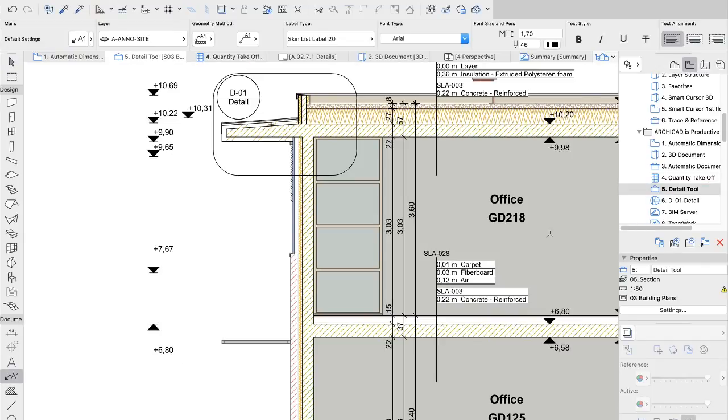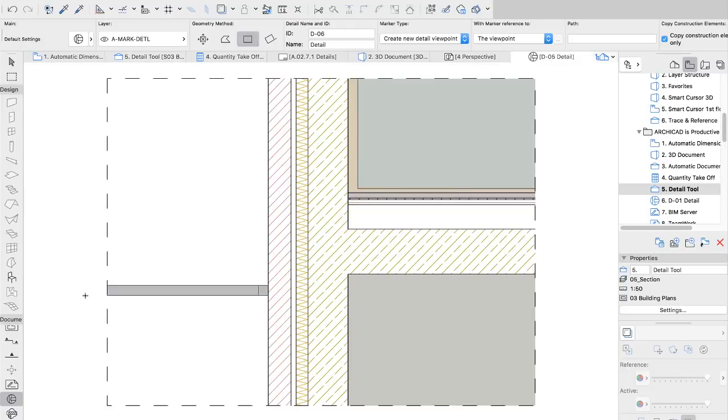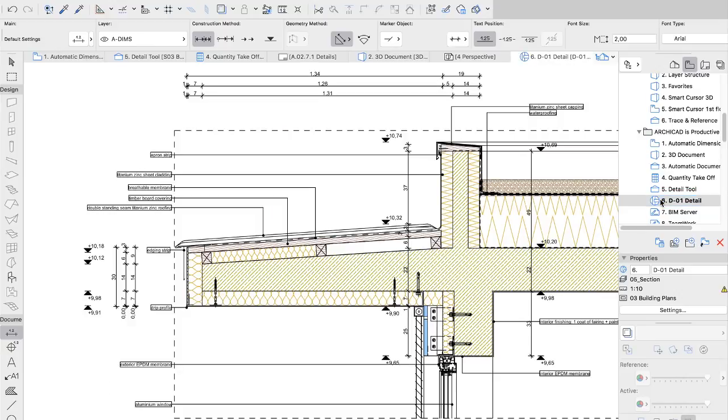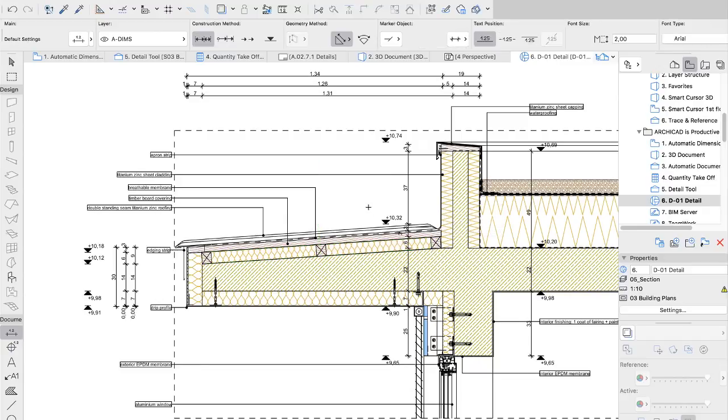When it comes to creating details in larger scale, you can use ARCHICAD's dedicated detail tool. The model elements within the detail's boundary will be automatically clipped into the detail window. And you can use ARCHICAD's complete 2D toolbox to finalize them. For example, you can just place dimensions on the detail. Or like in this case, the detail was further elaborated by 2D lines, fills, and objects. No need to finalize your construction documentation in another CAD software.